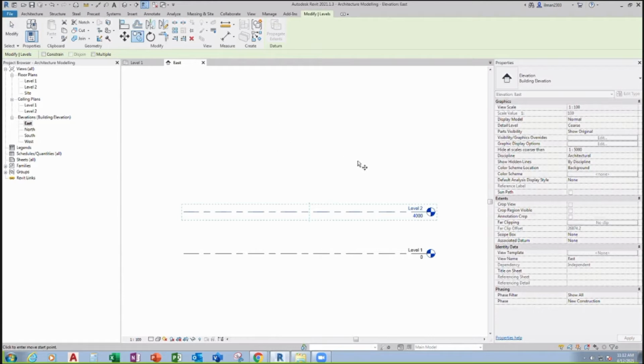Copy. First of all, you can see at your status bar, it's the same as AutoCAD. Once you are familiar with AutoCAD, the prompt is at the bottom. It will show you what you need to do. So click to enter the move start point.